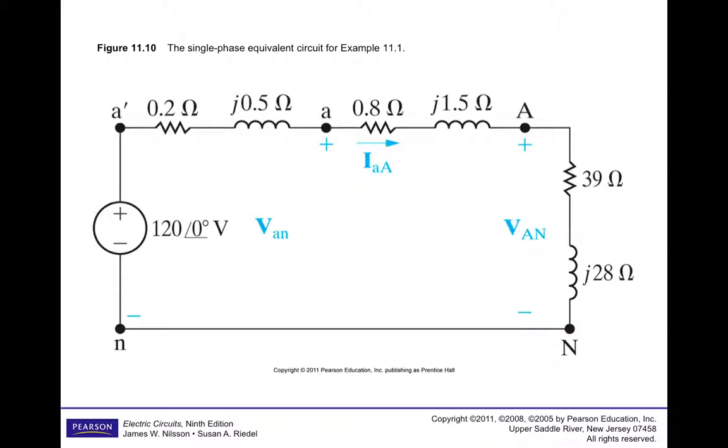Once you find the voltages in phase B, you can also find the voltages in phase C by taking the voltages in phase A and adding 120 degrees of phase. So it becomes very iterative, and you really only have to solve this one very simple single loop circuit. So the main key in three-phase is not to overcomplicate the problem, which is easy to do.